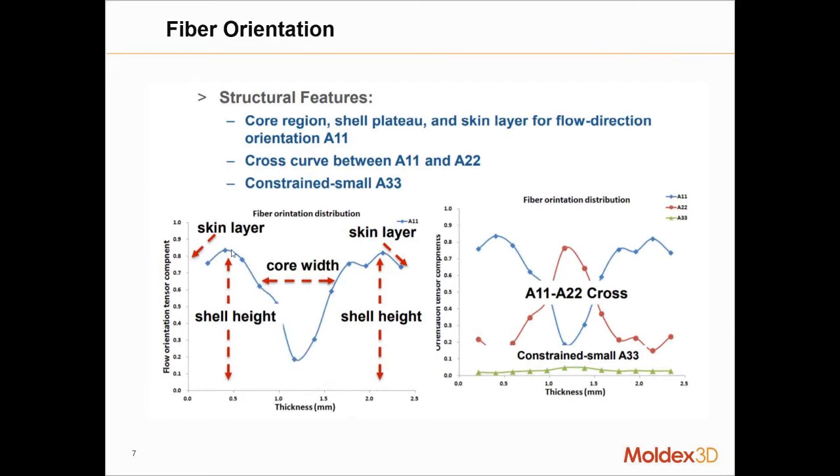But as we get towards the shell, the fibers themselves are getting flipped up and pushed up along the sides of the mold. They're getting pushed into the skin layer. Now the skin layer itself will typically have a slightly lower fiber orientation, because the material almost instantly freezes when it hits the mold surface. Whatever the fiber orientation is when that polymer touches the mold, it's just going to be locked in. There's not a whole lot we can do to control what happens at the skin.